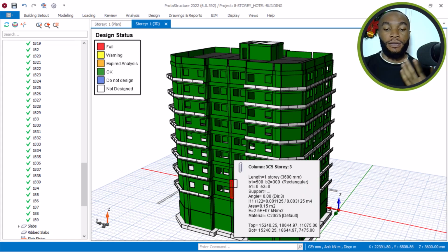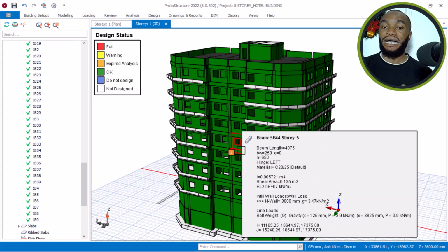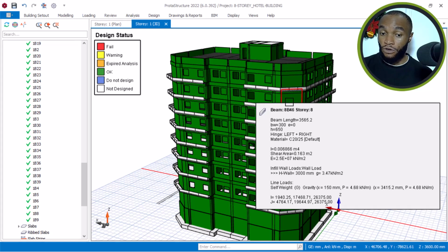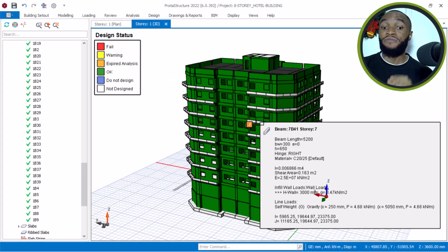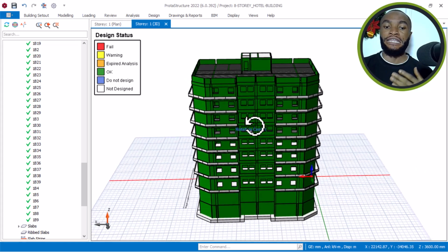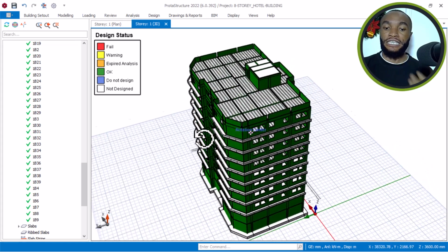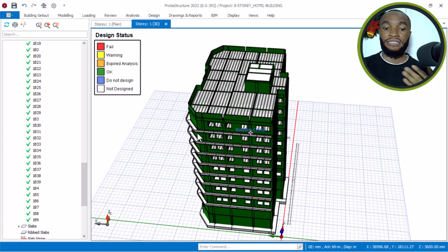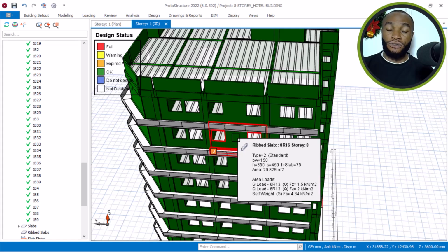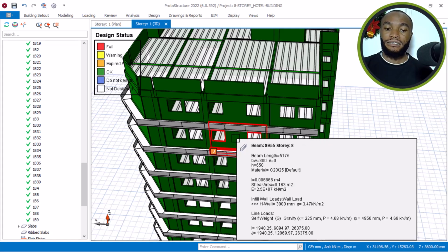Because most times the software can be giving you higher reinforcement or even under-reinforcement, and most times it can still show green. But that's in rare cases. If it's higher reinforcement, that's fine. You can see that a beam or a column that can be passing with T16, or let me say diameter 16, can go and pass with 25 diameter. That's because that's the software's output.